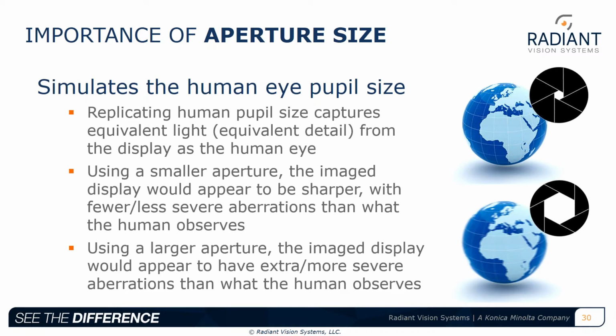But then we would be really limiting the light that could make it to our sensor, and so exposure times would be extra long. Any kind of vibrations would really affect the system. Making the pupil too large would make the optical design exceptionally challenging and much more expensive. So we have compromised on this specification, but we believe that it's a fair compromise.